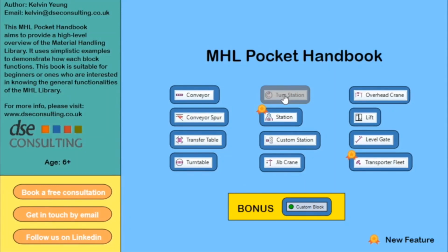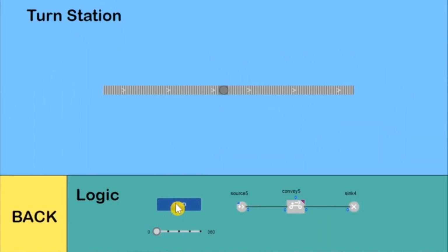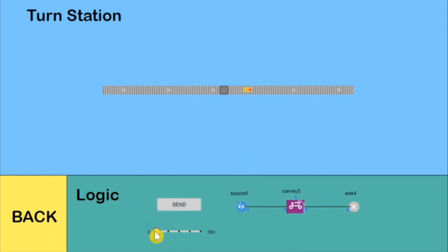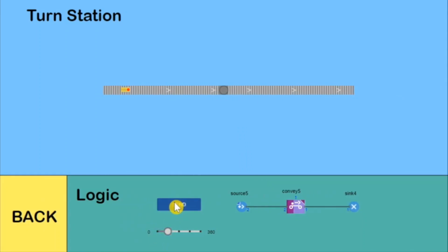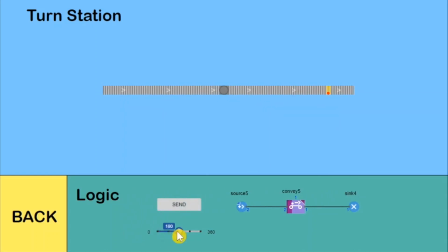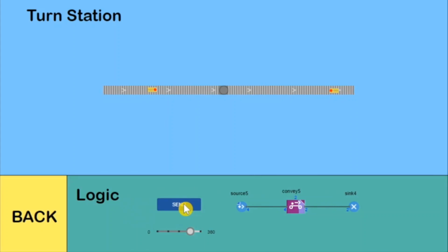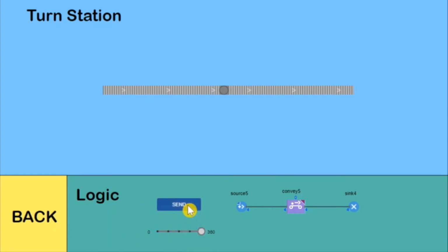Turn station. Turn station is a graphical space markup element that is used to define turn stations. Turn station rotates agents passing through it. Items can be rotated by any angle that is divisible by 90 degrees. Once placed on a conveyor, the turn station divides it into two independent conveyors working in the same conveyor network. Turn station can connect only two conveyors forming a straight line.